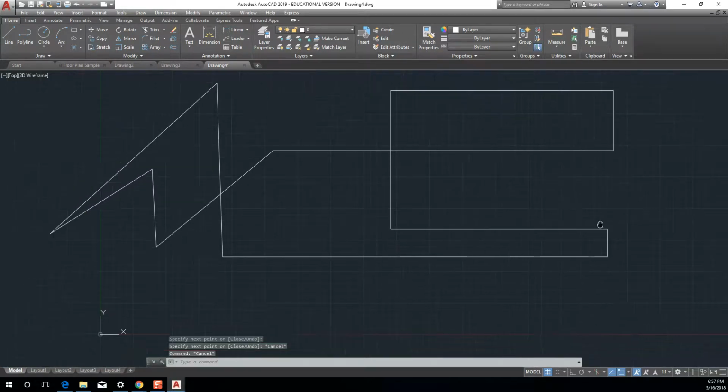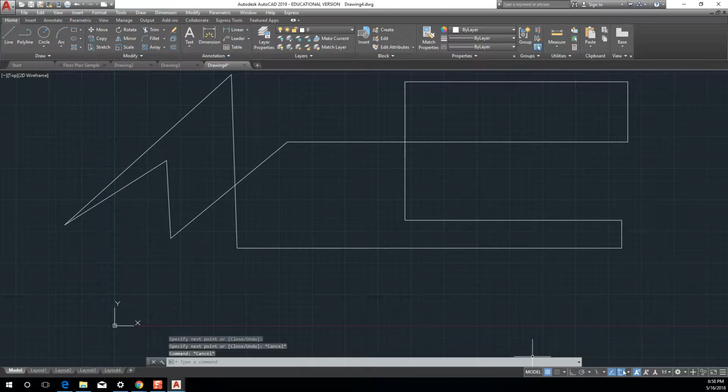Okay. So all of these different buttons down here are drawing aids, right? They don't all function like ortho, but they offer something. So we have the grid. If I click on the grid, it turns off, turns on, right? I'm not going to do all of these. I'll just do a few. Ortho helps you to draw straight lines.